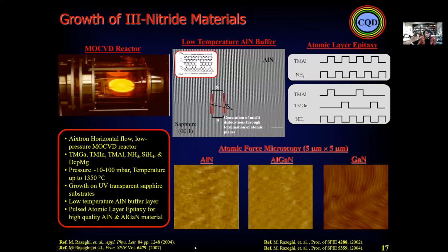I use sapphire because it is wurtzite, and at the same time large, so we can have excellent quality substrate. So now I have the epitaxy. I created and developed the MOCVD system, this reactor, in 1993 exclusively for this material, and I am still using the same reactor, and all of the results that we did and are doing come from this reactor.